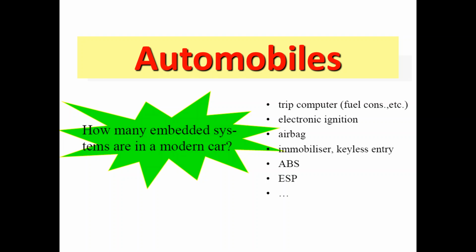The following are the key components and functions. First is the sensors and data collection. So we have LiDAR that measures distance by illuminating the target with laser light and measuring reflection. Radar that uses radio waves to detect objects and measure their speed and distance. Cameras that capture visual information for object recognition and lane detection. And the GPS that provides precise location data for navigation.